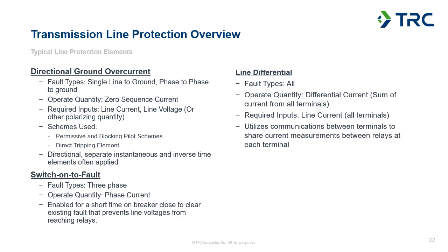Commonly in modern relays, we're using a voltage measurement for that, though you can do it with a transformer neutral current or a few other current-based methods for determining directionality, and we'll talk a little bit more about that in the next couple classes.